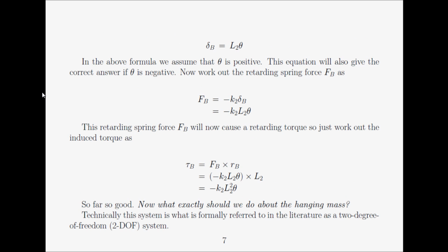If we had only one coordinate, let's say theta, the system would technically be called a 1 degree of freedom system or single degree of freedom system, sometimes just abbreviated SDOF. If we need more coordinates, which are independent of each other, but somehow connected, it is what's known as a multi-degree of freedom system, MDOF.